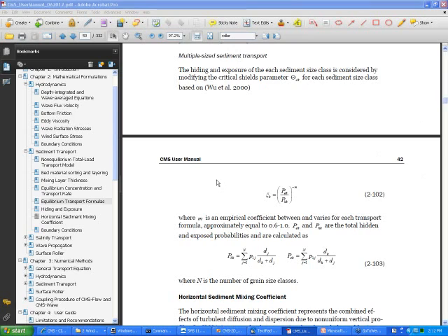So Allison has a question. Will a single D50 model simulation run a lot faster than a simulation with a set of sediment size classes? And the answer is yes, definitely. If you run multiple grain sizes, you might have 5, 7, 9 size classes. And what that means is you need to solve 5, 7, 9 transport equations and bed sorting equations and bed change equations and store all the bed layering and do those calculations too. There's a lot more computation involved with that.